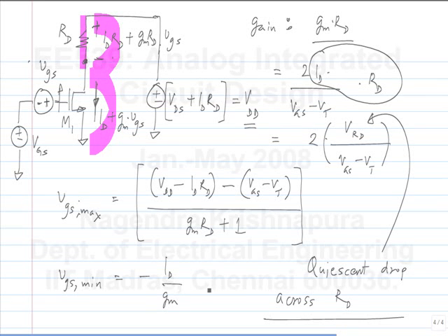Okay. Now, what is the swing limit you see here? This is VDD, right, minus IDRD, which is related to the gain of the amplifier, isn't it? So, if you try to increase the gain, your swing limit will reduce. So, this comes out as a sort of fundamental relationship. If you want a larger gain, you have to have a larger drop across the drain resistance, and that's the only way to get larger gains. Okay.